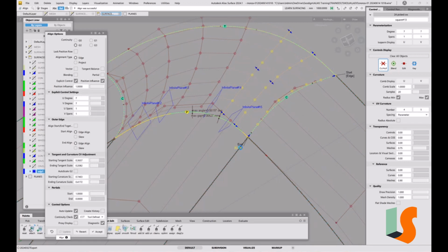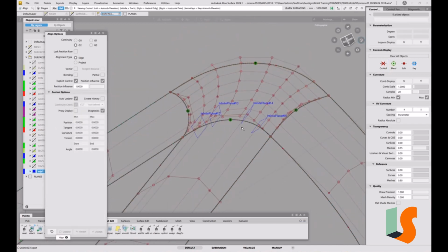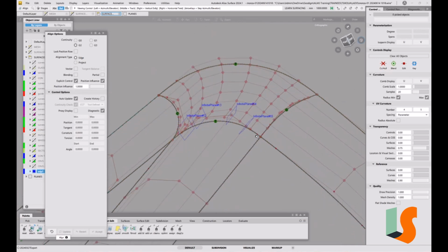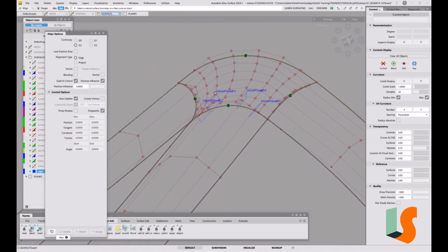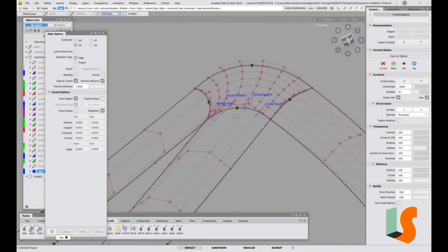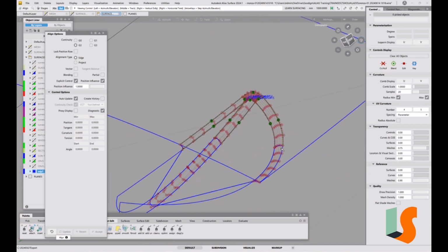Maybe if I put skew on there. Whoa! So it's just relaxed it a little bit, rather than saying it's got to go tangent into there in terms of that line. If I just say, well, I don't really care, which is what skew's saying. I think that's the first time I've managed to find skew has actually helped us, but it's always worth a try. Just relaxes the solution a bit more.